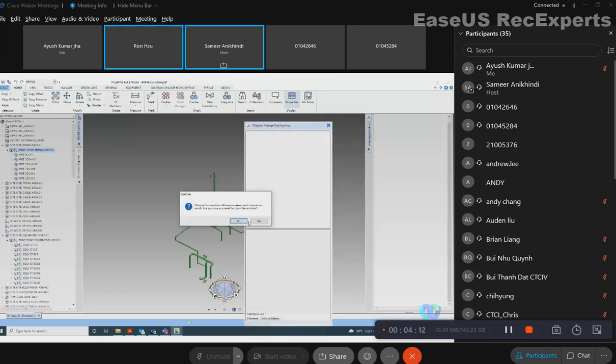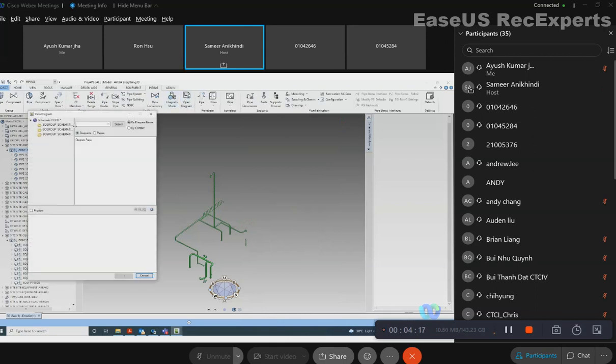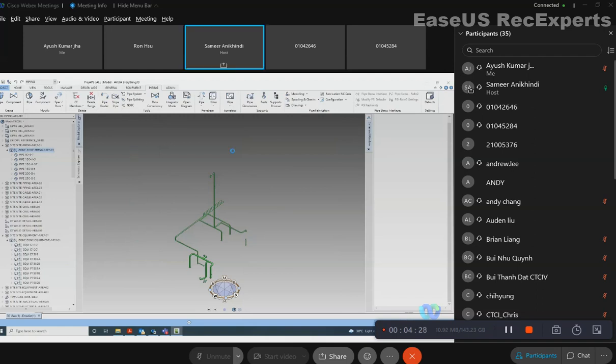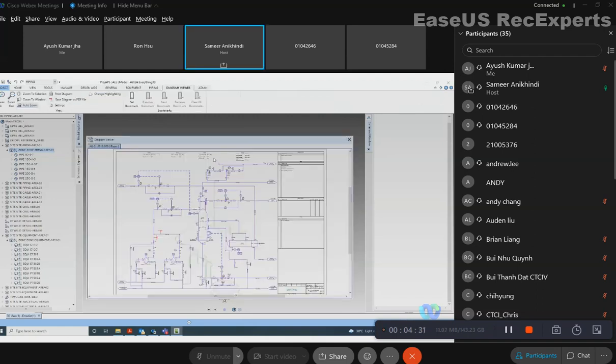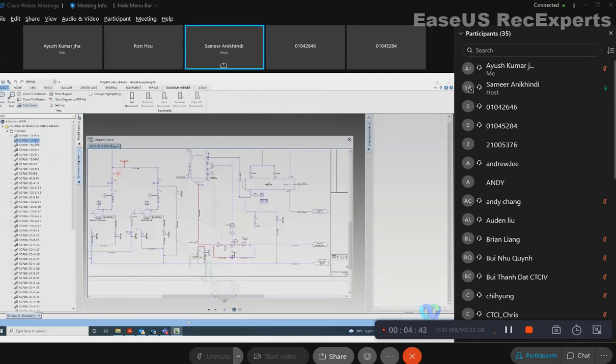So I will go to, let me close this. Piping, open diagrams. I will search by content, say 100-B-2. So it is there in this PNID. Click OK. And you can also navigate here in Schematic Explorer. Pipelines. This is my 100B2 line.